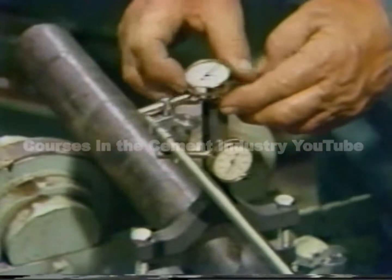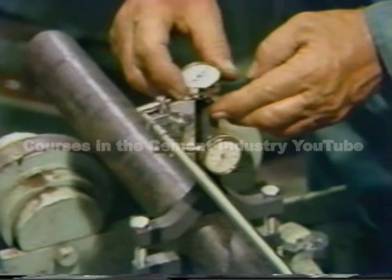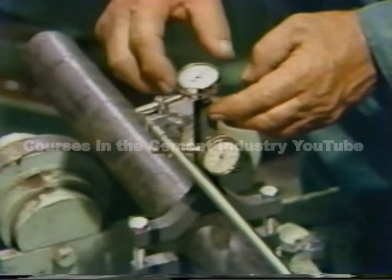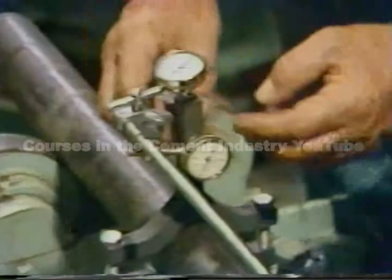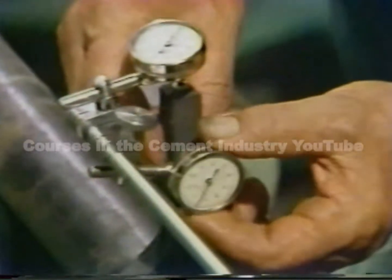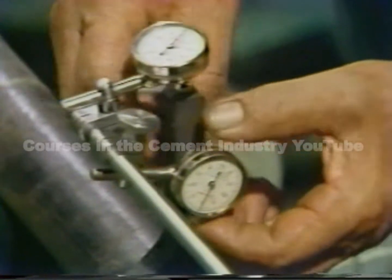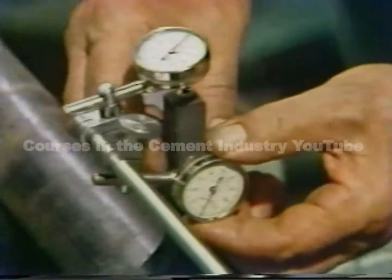Once mounted, the dials can be zeroed. A light tap on the mounting bracket will indicate that the mounting is rigid if the dial returns to 0 each time. The same is done with the dial mounted on the face. Slight taps will indicate if the mounting is secure.